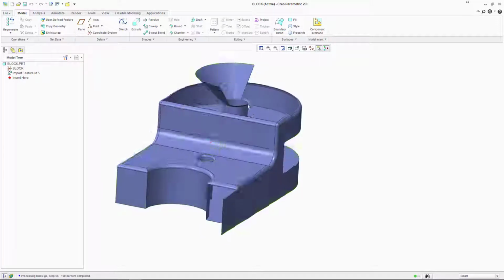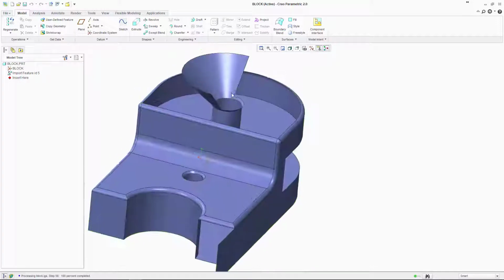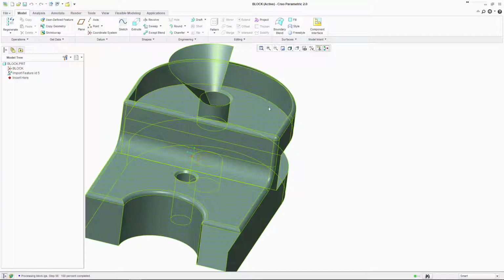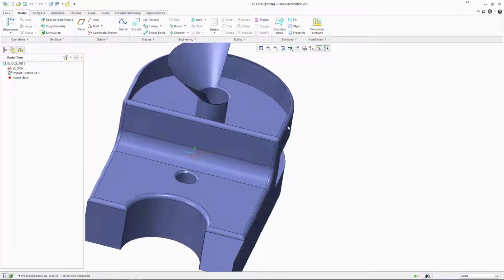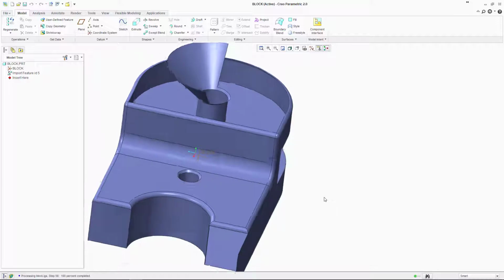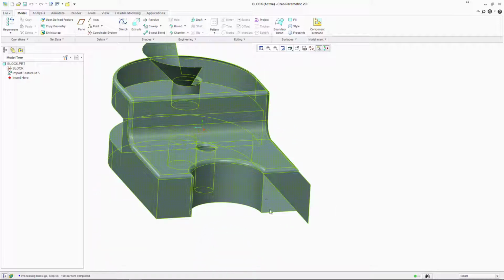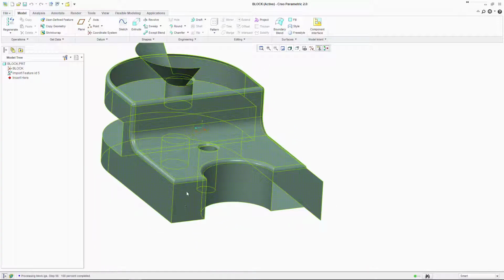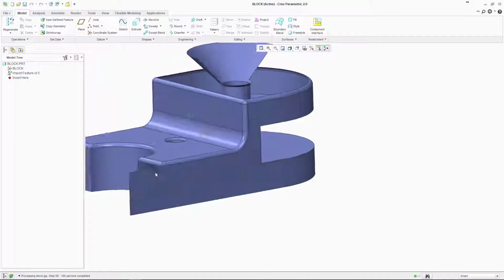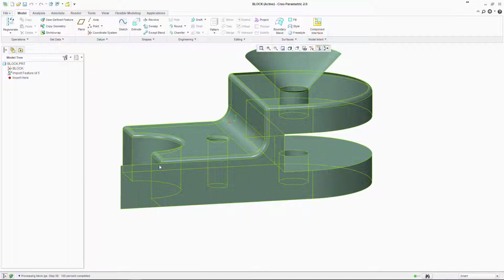You can see that there's a chamfer on this hole on the top, and one of the surfaces of the chamfer is extended well beyond the top surface. There's a missing surface on the top face here that appears as if it should be there, a flat surface or a planar surface if you like. And then there's a hole down here which appears to be filled on this side but is actually missing on this side, and then there's an overhanging surface here as well.